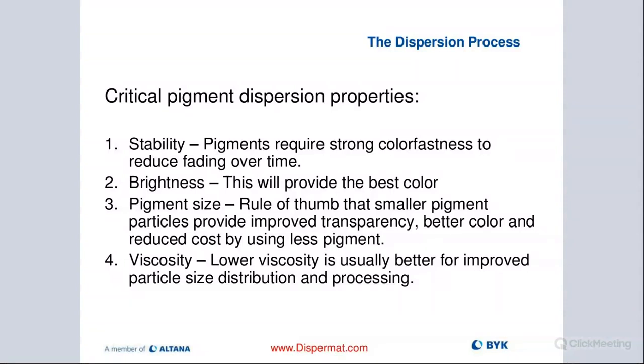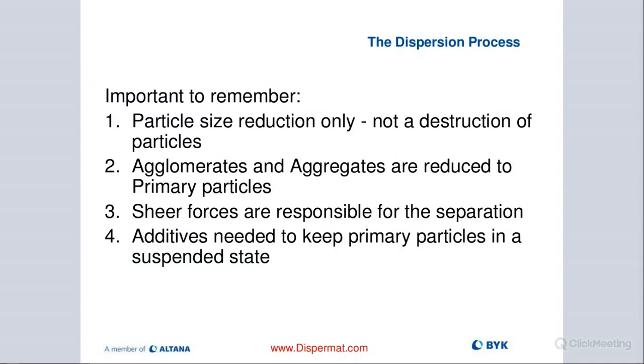That would be optimum to put in the good amount of energy that we need to really break up these van der Waals forces. If the viscosity is too low, it's very difficult to put in the energy. And if we are too viscous, then it's sometimes too difficult to get good processing parameters with the blade. And also if we are milling, it's difficult to get the product through the media mill.